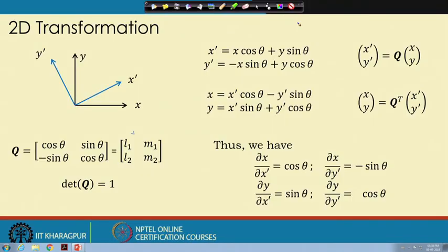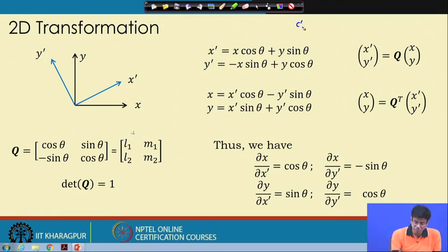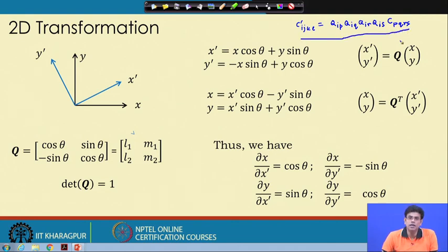Now here we also know that the constitutive matrix is a fourth order tensor, and this fourth order tensor transforms through the ijkl formula, Q_ip Q_jq Q_kr Q_ls C_pqrs. But with this formula, it is impossible to write it in a matrix notation.